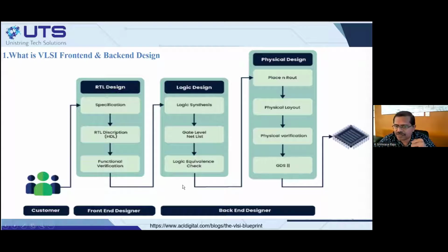You can do one simulation called a timing and placement simulation, post place and route simulation, as people call it. People usually don't do it for big designs. They occasionally do it when they have to do a lot of troubleshooting in the FPGA industry. In ASIC, maybe it's a standard practice because the cost of making one chip and manufacturing it, then realizing there's a mistake, is huge. But in FPGA, it is not.